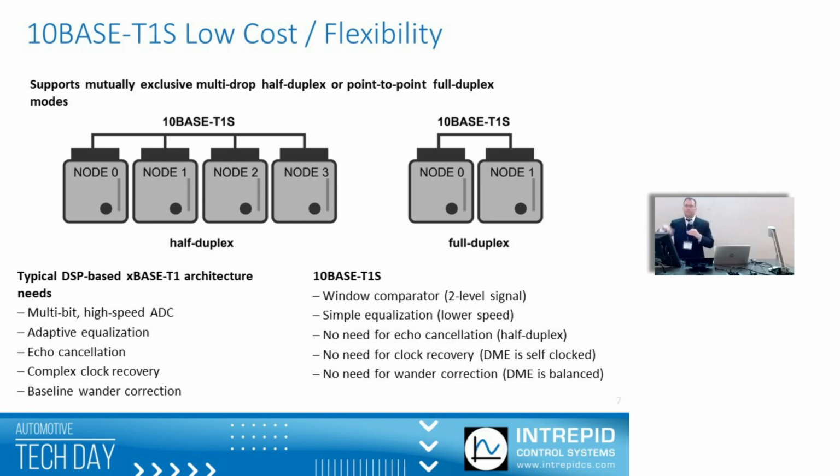So switches for 10BASE-T1S do not have to change at all, except with the restraint that if you want to connect the 10BASE-T1S network to a switch port, that switch port's physical layer, the PHY, has to be 10BASE-T1S, naturally, because 10BASE-T1S is not compatible with any other form of Ethernet. Good question.